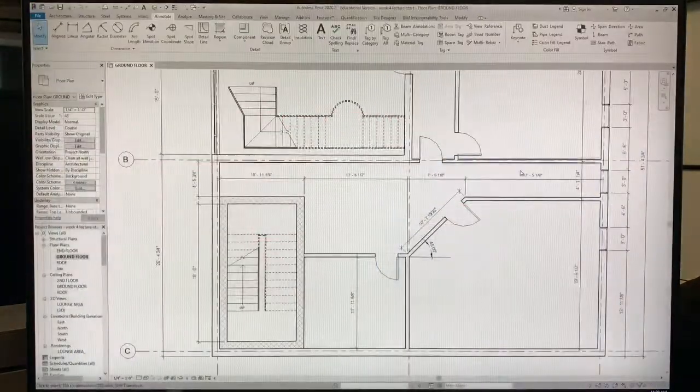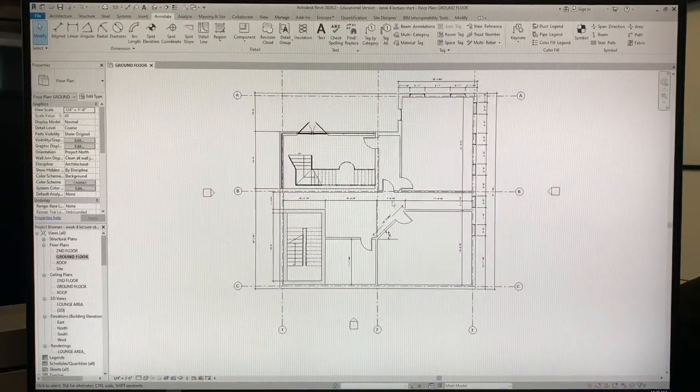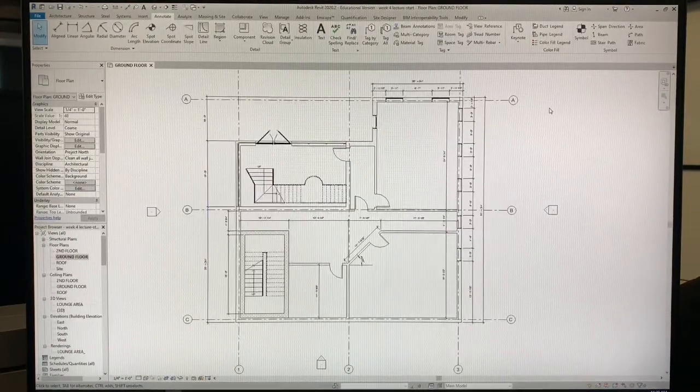All right, dimension styles. Okay, how do you control dimension styles? Now, when I control my dimension style, the very first thing that we need to make sure we do is make sure that our annotation scale is correct, because obviously your annotation scale is going to control the size of your dimensioning and all annotative objects, okay?